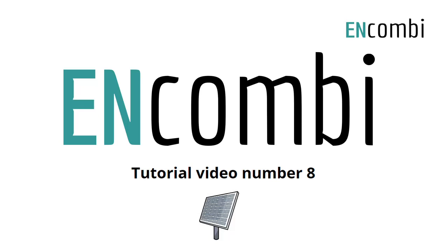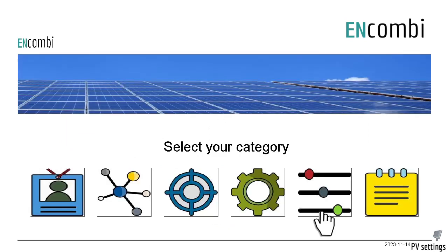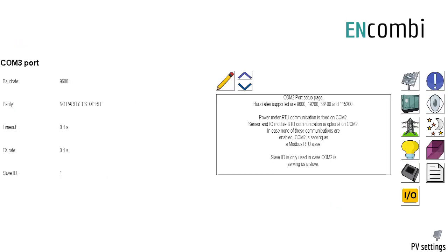Incoming Startup Tutorial. Tutorial video number 8. PV Settings. PV Communication Settings is available under the Setting category of the EC Web. The Incoming Controller uses the Modbus RTU Communication or TCP Communication Protocol to receive readings.